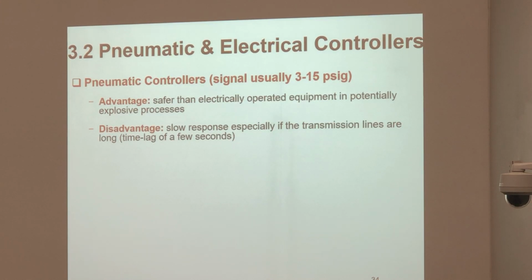Safer. Mainly because if the area has flammable or volatile product, I cannot use electric. If I use electric, it can cause an explosion, things like that. In that case, the entire control system in those areas, I have to use pneumatic. Pneumatic means I only use gas to transmit my signal. If I want to turn on the valve or the pump, I use air pressure to push it open. If I use electric, what happens? The electric creates a spark, and the entire thing will cause an explosion. So it's safer.